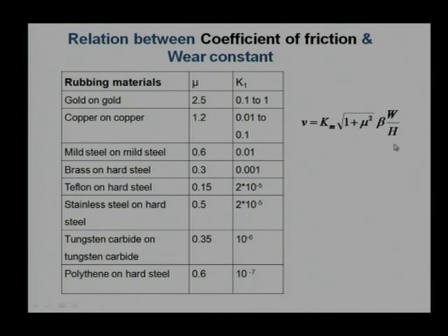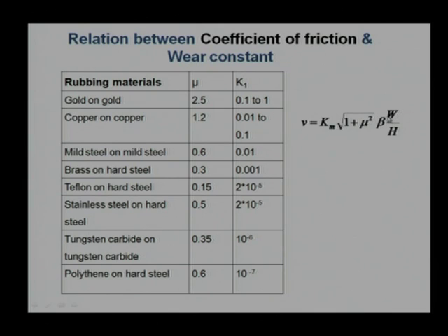This beta indicates the lubricant layer thickness, how much area has been occupied by the lubricant layer and how much area is the dry area. So, beta basically represents the dry area with no lubricant layer, and it will be less than 1. In other words, 1 minus beta times the area is covered with a lubricant.